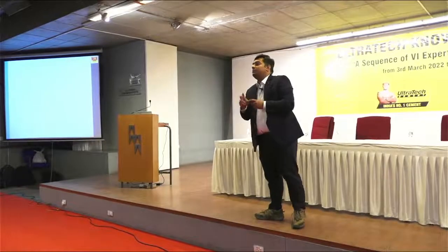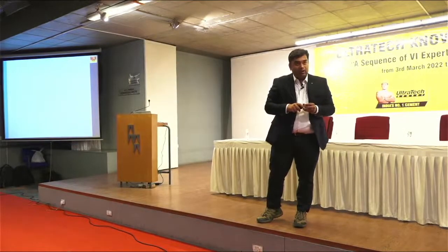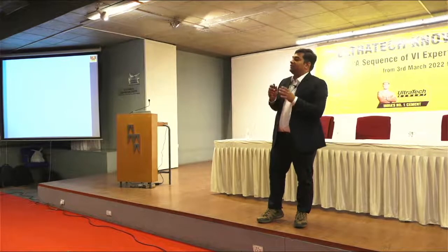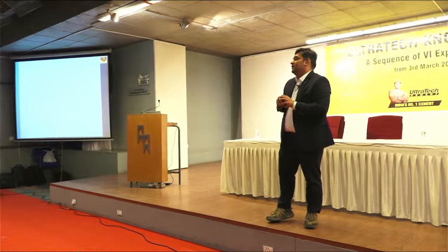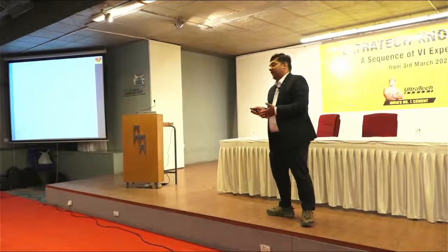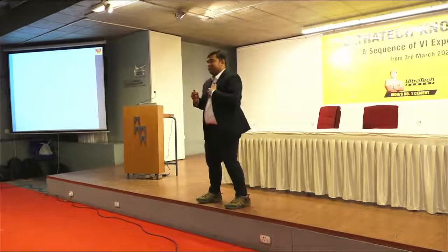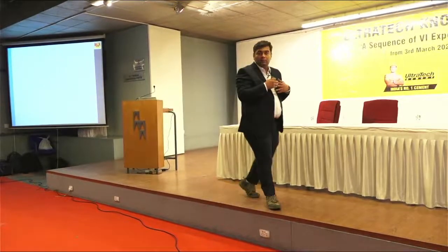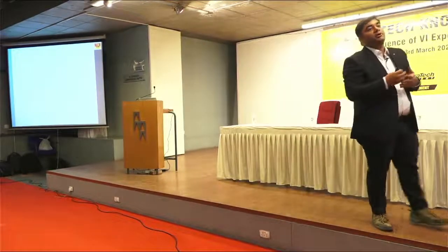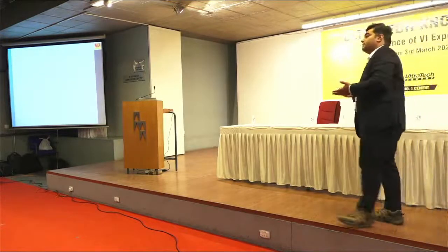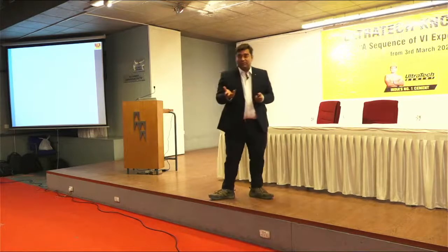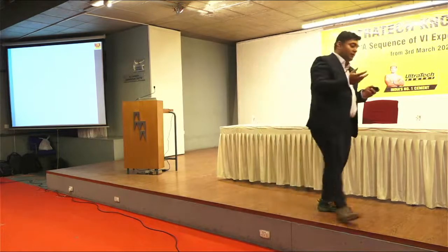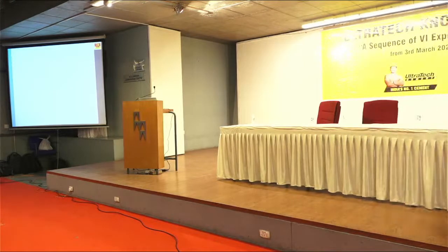Fine. So the cement paste plays a very important role in concrete. Wherever there is more cement paste in concrete, what will happen to the concrete? If cement paste is more, then the concrete will dry and there are chances of cracks. True? Because of the more cement paste. If the cement paste is less, then what happens to the concrete? The concrete will remain porous. Or you can say it will cause honeycombing in the structure. So in both the cases, durability will be affected.